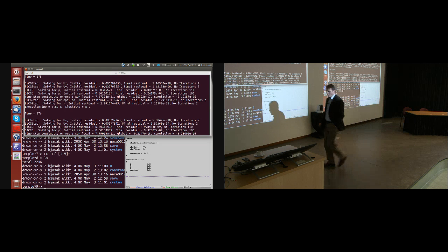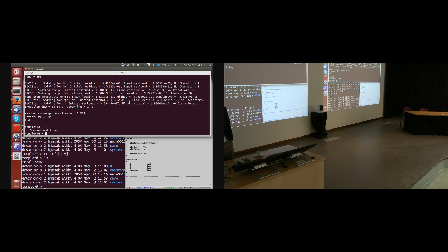By now this should have converged. And you can see here it says reached the convergence criterion 10 to the minus 3 in 595 iterations, which means that the biggest number of 5 10 to the minus 6 blah blah blah is less than 1 10 to the minus 3, and that says your solver has converged. Okay? In many cases, you will see the pressure being the last variable to converge, which is quite typical for the segregated algorithms.